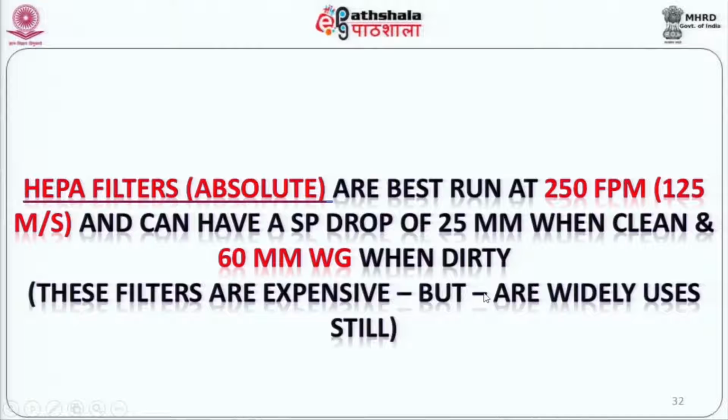You never can reduce it to zero, but you can minimize it to a lot. This would ensure that basically dust is not there, and if dust is not there, you are very certain that bacteria and virus will not find a way in. So it's an indirect control on sterility imposed by good filtration. These filters are better run at slightly lower velocities than the other filters.